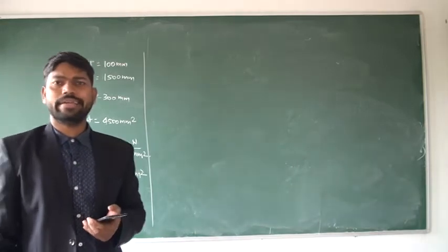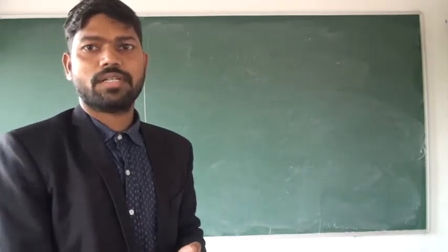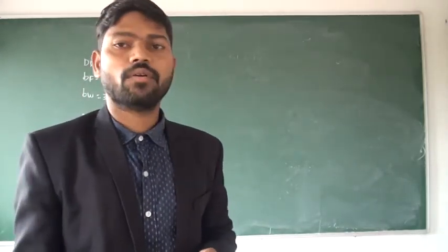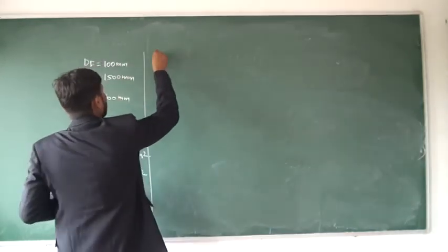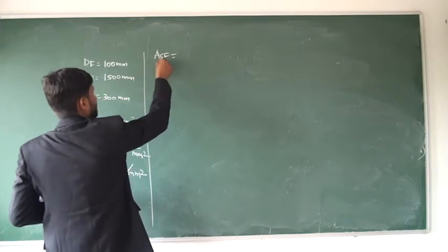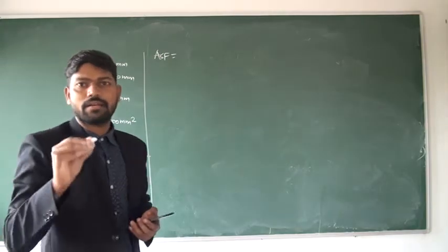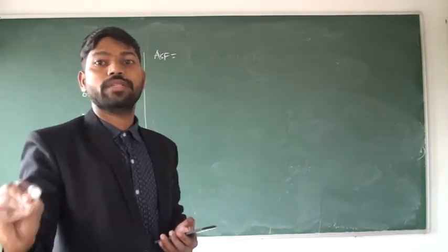Again, we don't know which case it belongs to. So first we will find out the case. Again we will calculate the ASF value. ASF represents the steel required for compression to be within the flange.